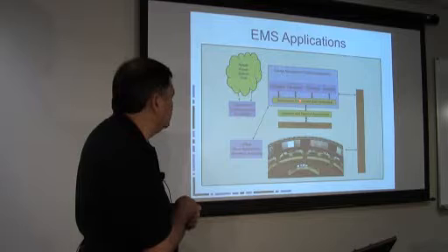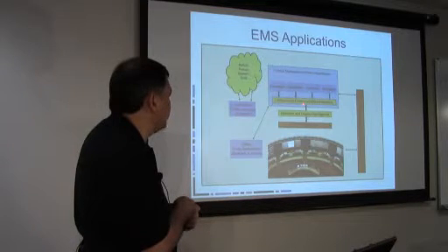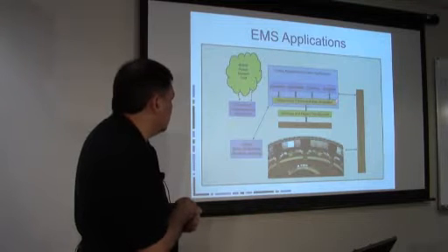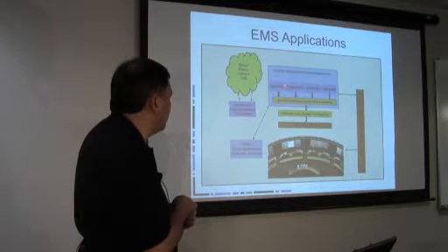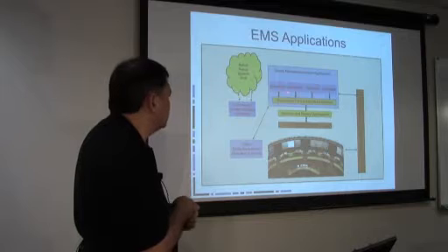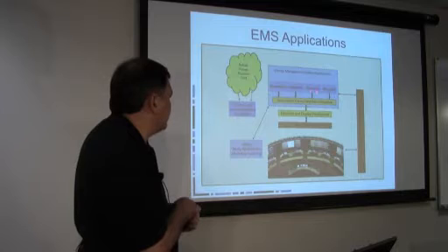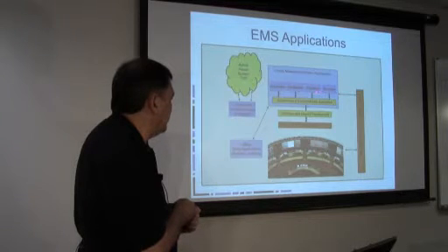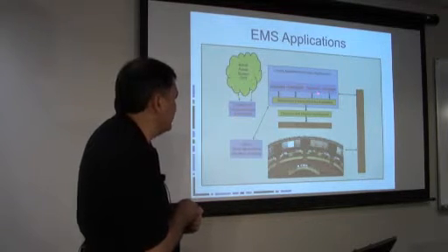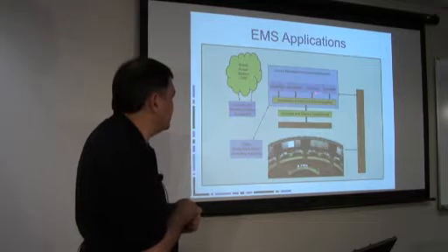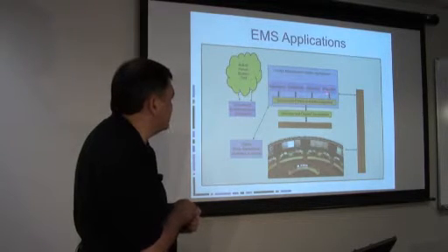So again, this is the supervisory control of opening and closing breakers, controlling transformer taps, and the data acquisition part. Then those applications provide the right data to support the generation apps, which is the automatic generation control, the transmission applications, which model the power system, and then we can have the dynamic applications, which are looking at whether the system can be stable. That's the next generation of application. And then we can have a simulation mode.